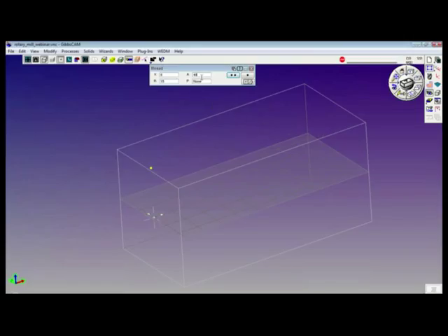Now those 48 threads are multiplied by 360 degrees because each thread does a full revolution. 48 multiplied by 360 degrees, and the radius remains at 1.5. I'll click on the single feature creation tile. The point appears at the end of the part, and it looks no different from the first point that we placed in linear mode.